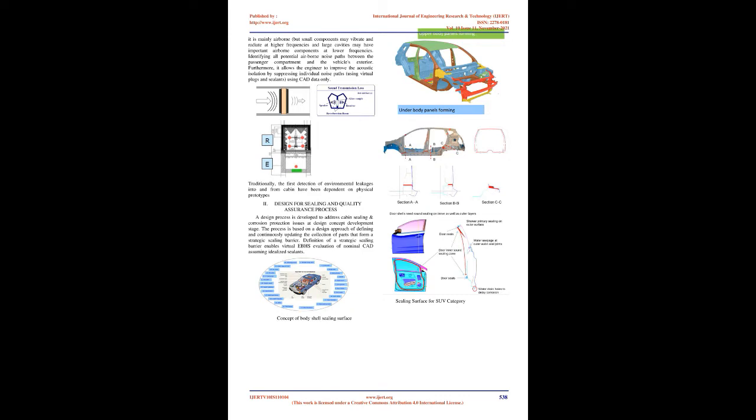Key points. 1. Need of digital analysis. Body shell baffle location digital analysis for sealing of airborne and acoustic leakage. 2. Preparation of single sealing surface CAD data with reference to the latest release 60R CAD data. 3. Review the sealing surface by taking various sections and checking for continuity of panel section. 4. Wherever the continuity is disconnected, check the same location in other sections for discontinuity. If yes, then it is identified as potential leakage.